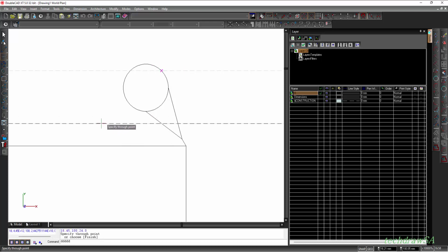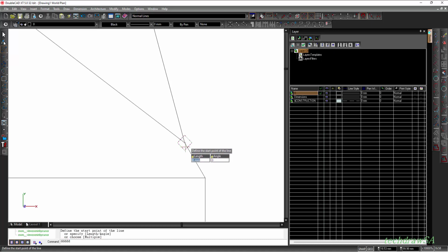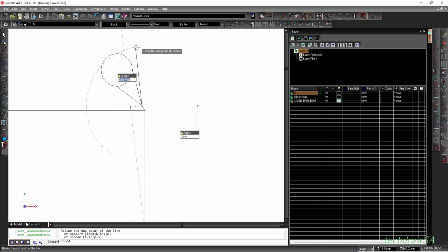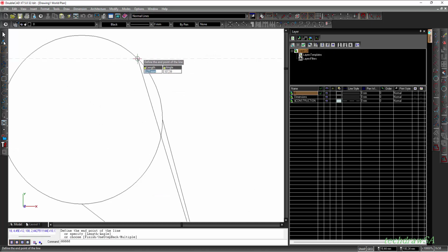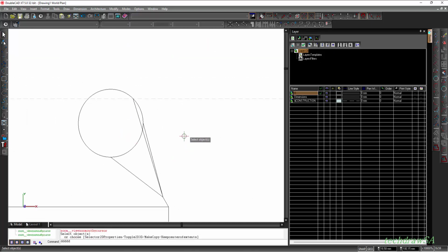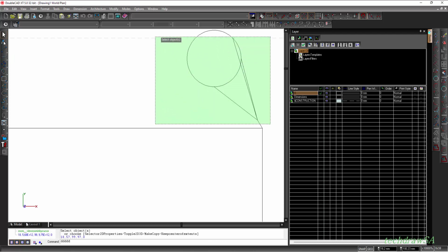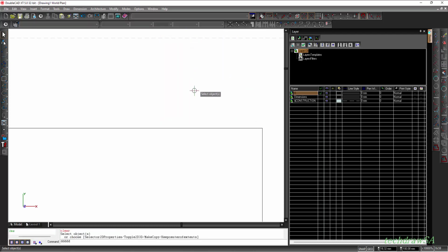I just place a waterline there, then I choose the line that I want to snap. I'm going to go to that end point that I want to snap from, draw a line from there, and snap it to that point and press escape out of that. Now I have that reference point for the snap. Let's clear all of this clutter by selecting the selector tool, selecting all of that and pressing delete.